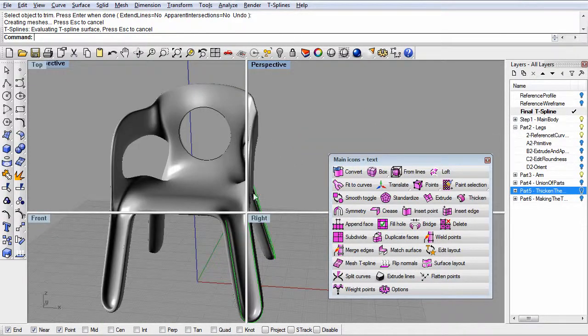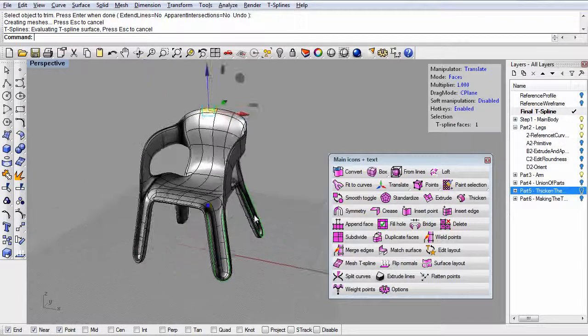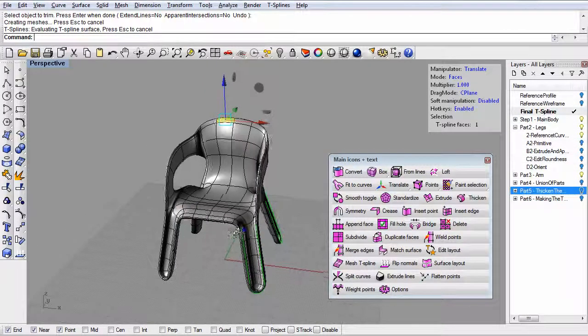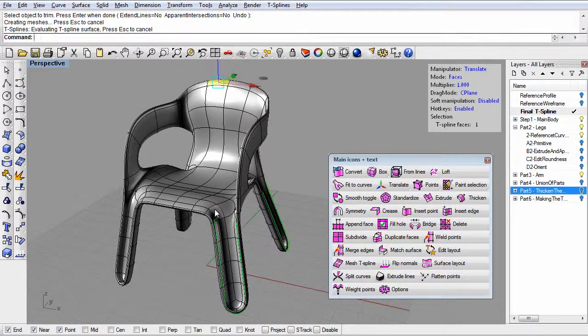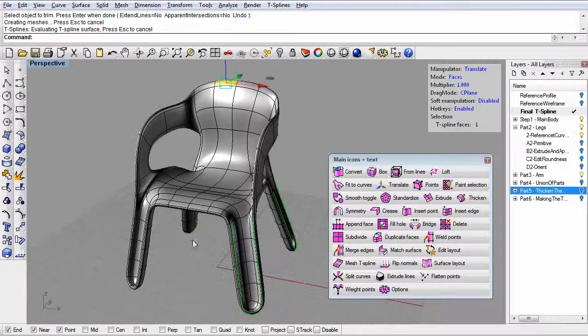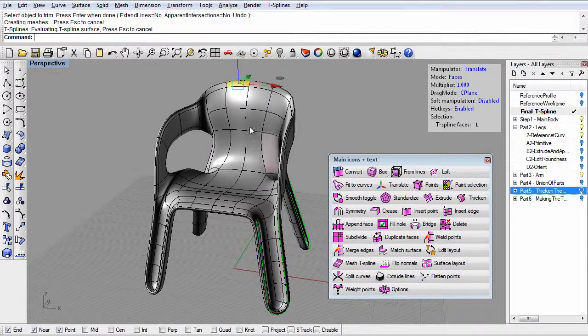One other thing is this T-spline will go downstream to any other modeling package beautifully. So if you wanted to go to SolidWorks or Pro-E, and if you want to thicken it using their tools, you could just export this model as a surface or a solid. And I've never heard any reports of T-spline models that have not been completely watertight as they've gone to other programs downstream. So you could have exported this as an IGES or a STEP and read it into other CAD programs, and pushing T-splines data downstream like that works really well.